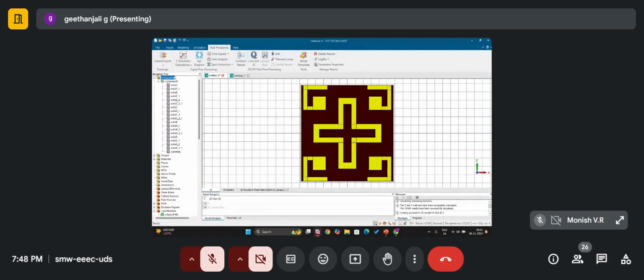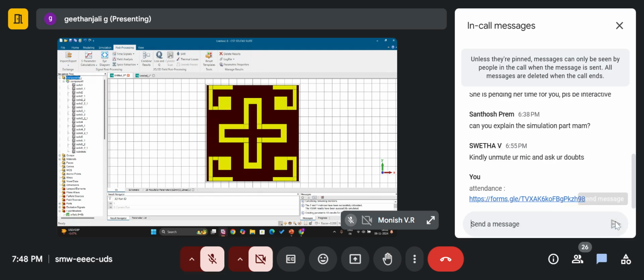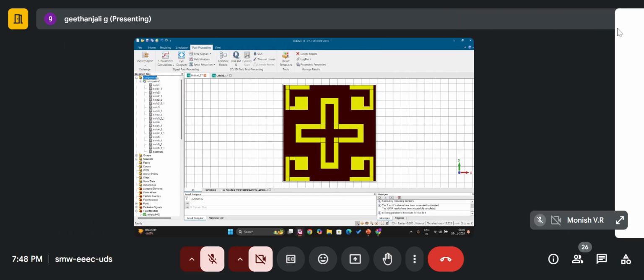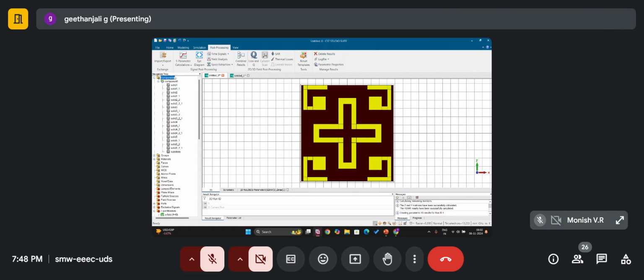Now the evolution of FSS from the start to the present. Researchers designed the band stop FSS first to achieve shielding characteristics, and they designed the band pass FSS to achieve communication characteristics. Nowadays there is a trending topic called multifunctional FSS, where they design the band stop FSS at the front layer and the band pass FSS at the back layer at the rear side of the structure, with the help of PIN diodes.